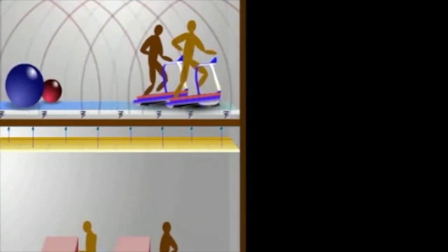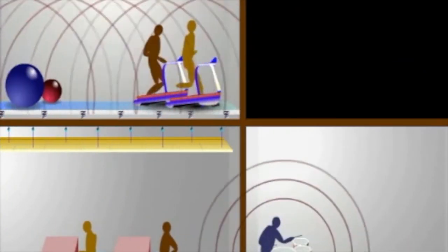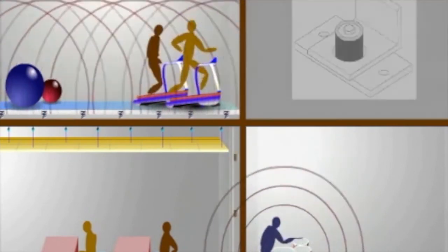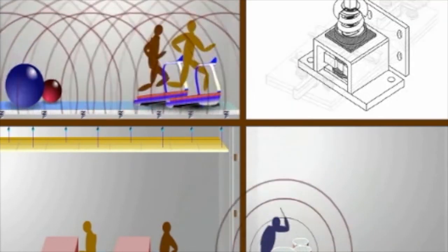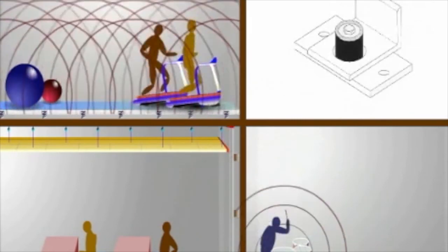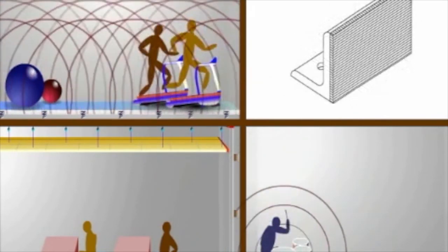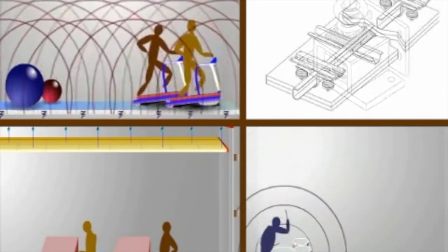If a classroom was located beside a band practice room, attaching an additional double layer of sheetrock hung with rubber isolators and attaching it to the ceiling using a resilient acoustical sealant would provide increased mass, airspace, and damping required for increased transmission loss.